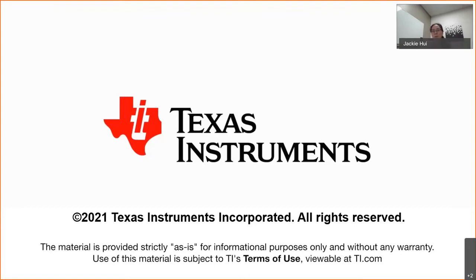A lot of our half bridge drivers are actually used in a full bridge topology, and the same applies, that you want to try to reduce your inductance to have good layout. The best thing is really to pay attention to your layout, because it pays off big time. I would say it's much easier than trying to find external components to work around the problem.